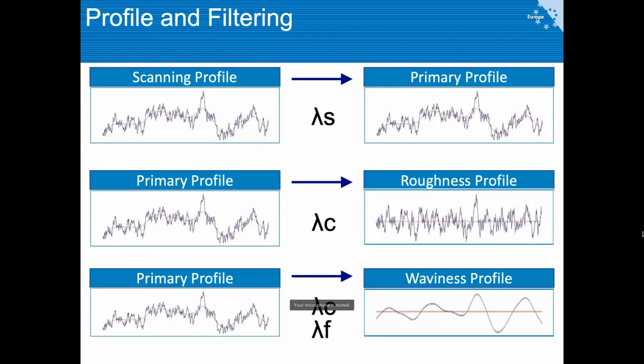What this filter does is simply remove very random and very small oscillations, which might be a result of some sort of vibration of your tool itself. Let's say your measurement tool has a cooling system, a ventilator, and it might produce small oscillations, and your measurement is so sensitive that you can actually feel these small oscillations.